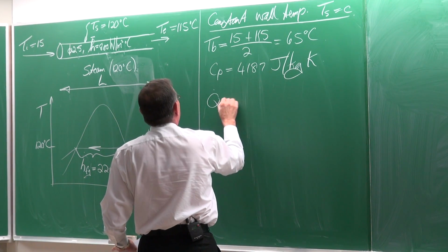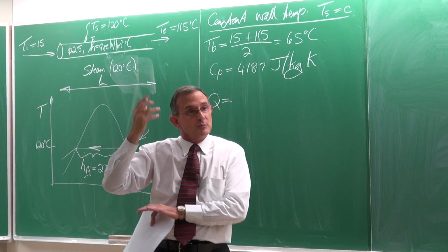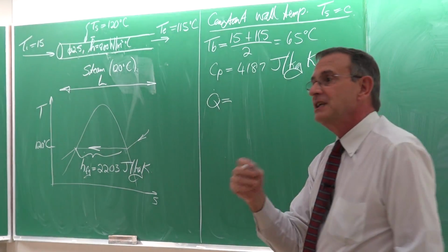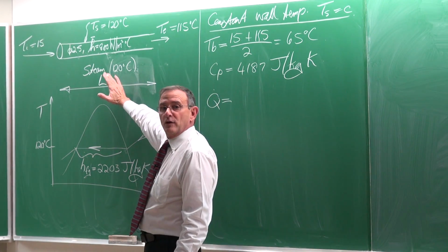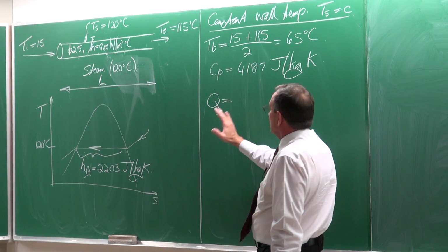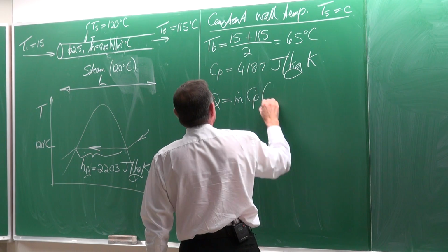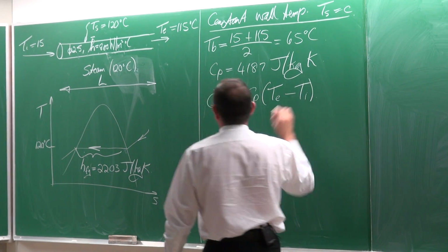Many students typically would look at a problem like this and immediately want to become too complicated, and you do not see that you can actually calculate one of the most important things just by saying that the heat transfer rate is equal to the mass flow rate, the Cp, multiplied by the outlet temperature minus the inlet temperature.